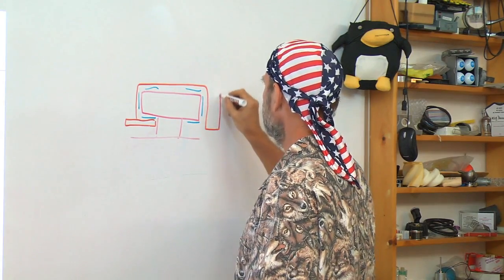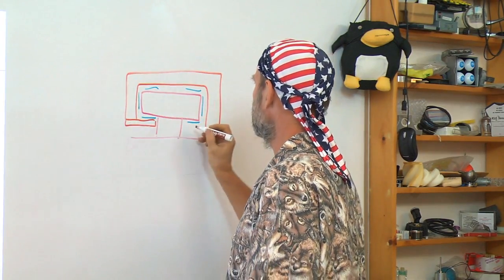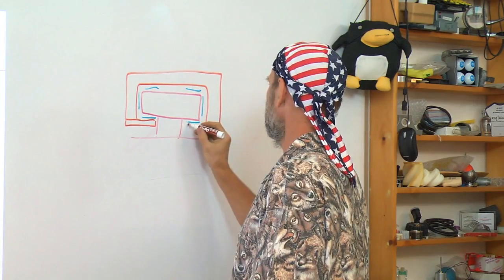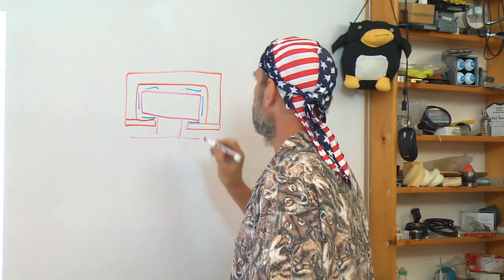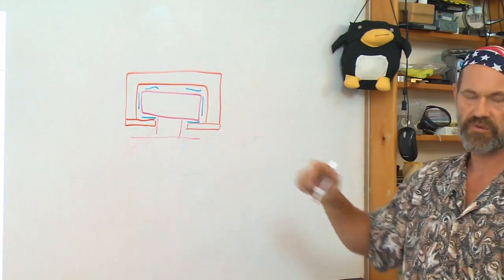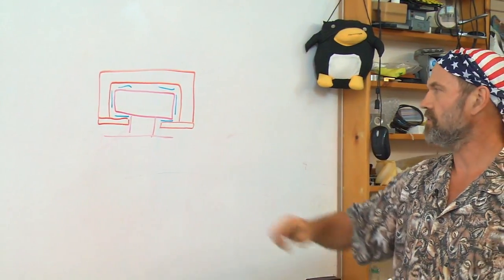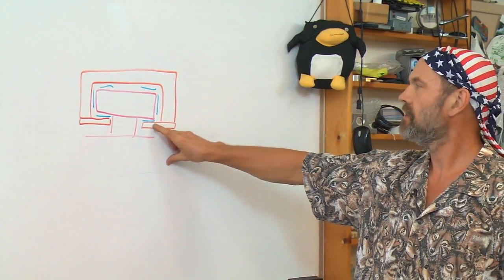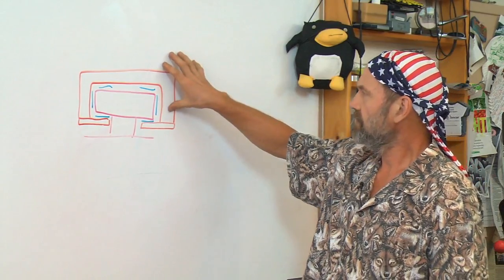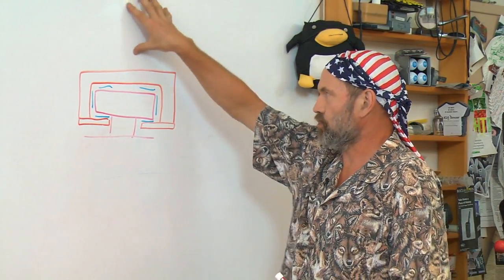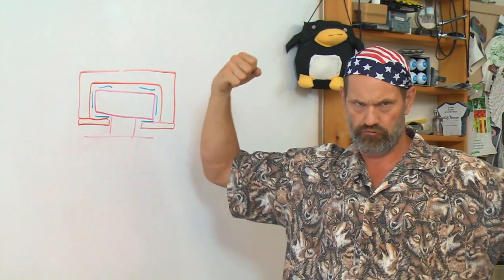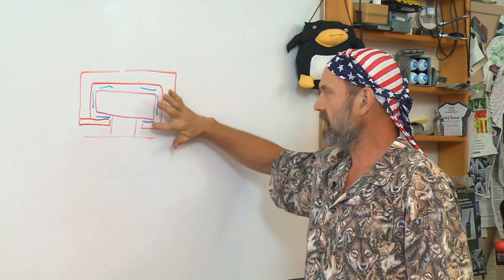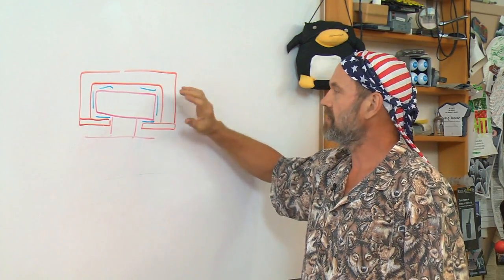Here's a very good thought question for you in a minute. Why did I draw these lower guys real thin? These are called keeper plates. For a machine tool slide, if I have big giant loads up top, why do I have these soft little keeper plates?